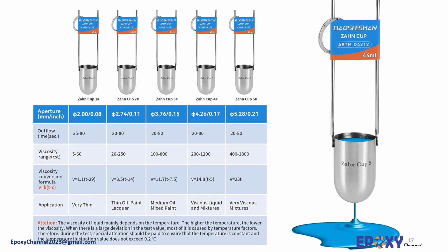The cup is filled with the resins to the marked known volume. The nozzle is then left open and the fluid flows through the nozzle. The time is measured until the drips of the fluid appear. This time is used in a similar way to calculate the viscosity.